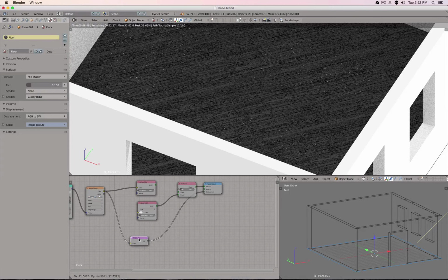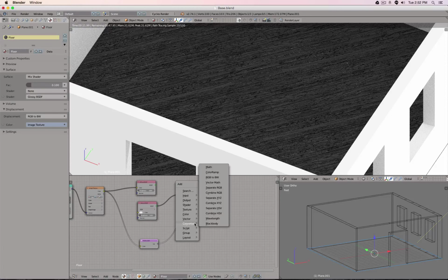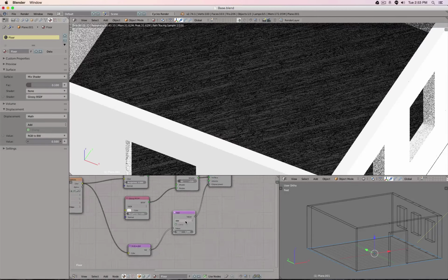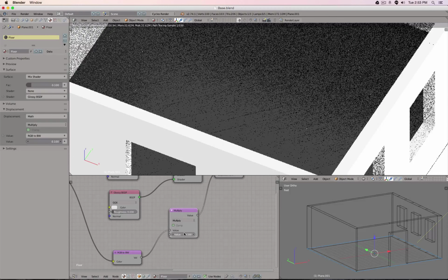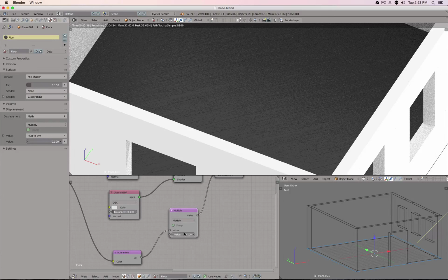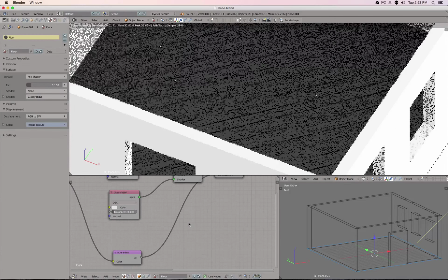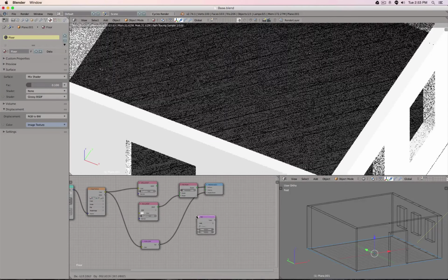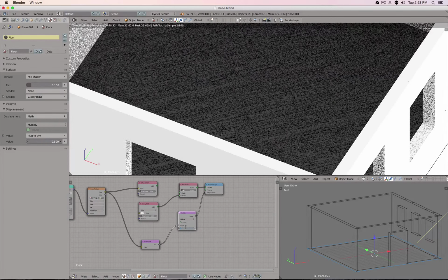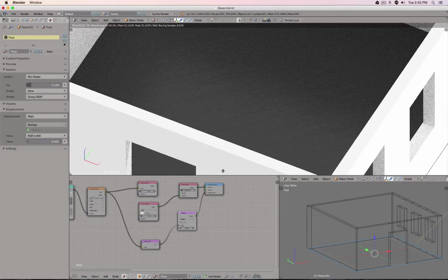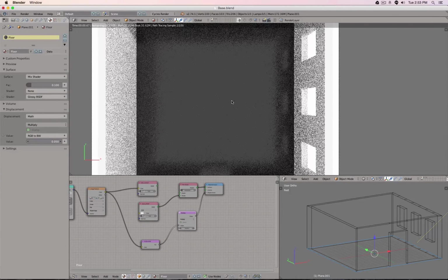So I need to be able to influence the values that go into this place, and we can do this simply with Shift A, converter, math, drag this on, say multiply, and maybe 0.1. There we see now, there it is. It looks a little bit better. By the way, in case you have something like this, not a big deal. We can just by hand connect these lines. Works exactly the same way. Multiply 0.05. Yeah, okay, let's go back into the top view.